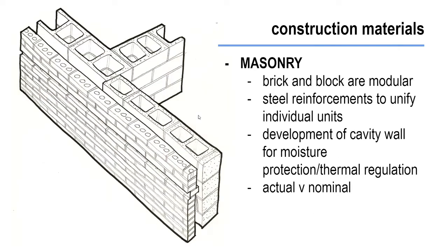In addition to concrete, we then have masonry forms, which is just what we have our CMUs, which are concrete masonry units, which are pre-made, and we use mortar to connect them with joints. Mortar is just a mix of cement and sand, and it's not as strong as concrete, but it acts as a very good glue. CMUs are often used in scenarios where a cavity wall is needed, and cavity walls are